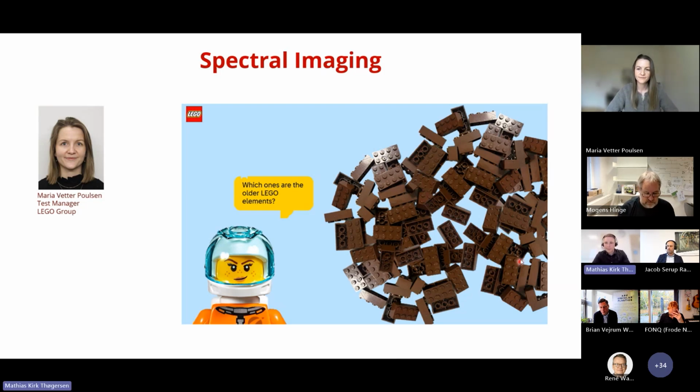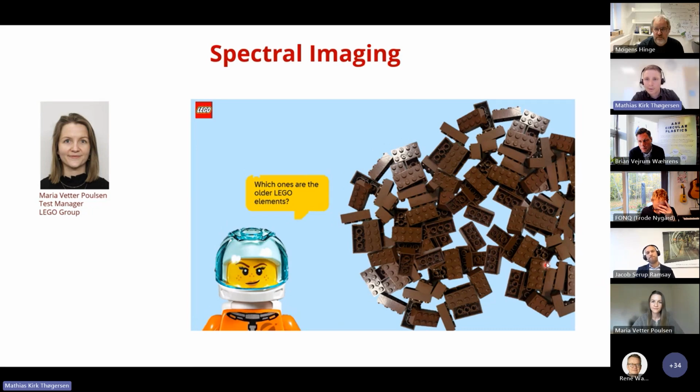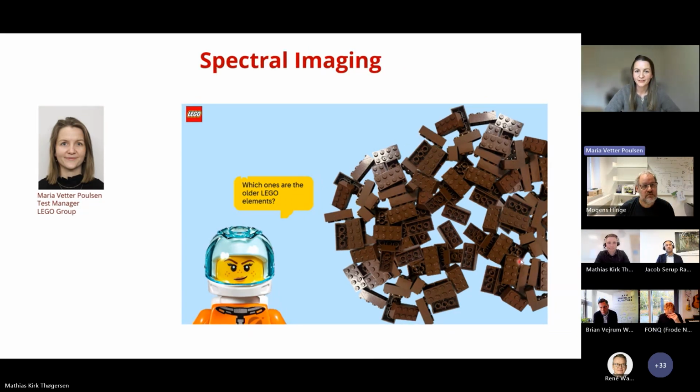Thank you. And I can see we actually got some questions here in the Q&A session. Mohammed asks if you can explain a little bit more on the analytical labeling process. Yes. So we spent quite a long time on this. That means we took each and every individual element. We gave them a number. We did FTIR, checking for the polybutadiene response. We have ABS, we have the styrene matrix, we have the polybutadiene. We know where we have the peaks. So we looked at the decrease here.